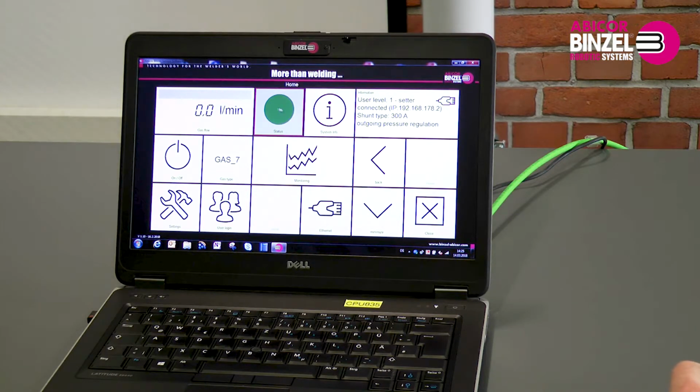The color of the circle shown here corresponds to the LED color on the EWR2. Green means that the device is switched on and there is no error. Blinking green and orange means that the device is turned on, but there is an error. Red means that the device is in bypass mode. A blinking red-orange indicates that the device is in bypass and there is an error.